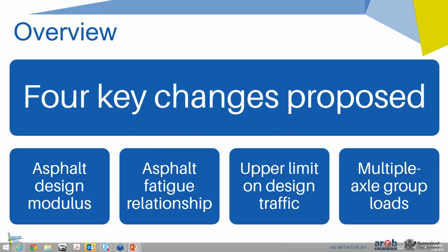The proposed technical note can be summarised into four main changes compared to current pavement design procedures. These are changes relating to the asphalt design modulus and the asphalt fatigue relationship, an upper limit on design pavement design traffic for assessing asphalt fatigue, and a new approach for considering axle loads.